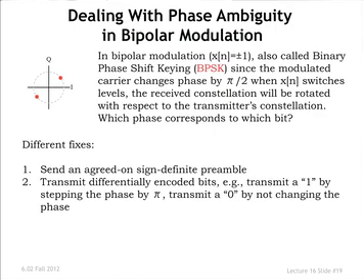And to transmit a 0, you don't change the phase in the next bit slot. So if from one bit slot to the next, the dot stays there, you know you've just received a 0. If from one bit slot to the next it flips over to the other side, you know you've just received a 1. Okay, so even with the ambiguity, if you change the way you code at the sending end, you can actually compensate for this. Okay.